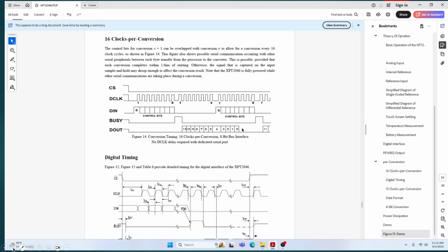Those 4 less significant bits are going to be part of the 4 most significant bits of your message. So when you get the message, you have to grab the 4 most significant bits. In other words, first I get the first 8 bits and grab the whole thing, and then the next thing I do is I get the 4 most significant bits of the next message, and that's going to give me my 12-bit value.